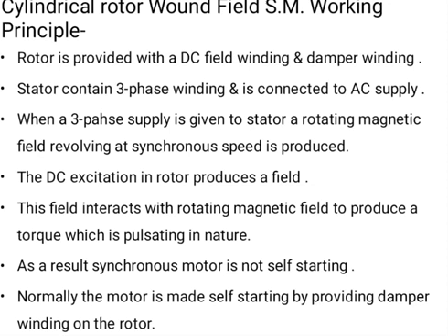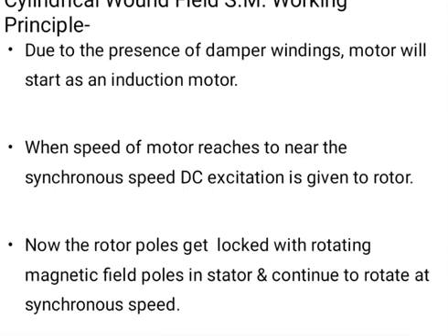This field interacts with the rotating magnetic field to produce a torque which is pulsating in nature. As a result, the synchronous motor is not self-starting. Normally the motor is made self-starting by providing the damper winding on the rotor side. Due to the presence of the damper winding, the motor will start as an induction motor.